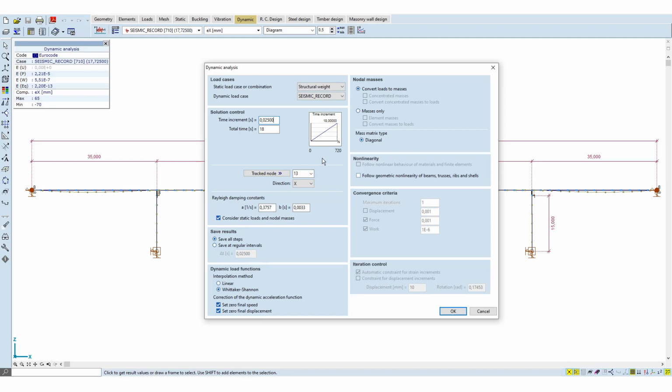The frequency domain we have to consider for Rayleigh damping is the two dominant natural frequencies, which are 0.7 Hz and 4.1 Hz. Based on these values, the coefficients can be determined with the formula shown in the theoretical background presentation, considering a damping of 5%.